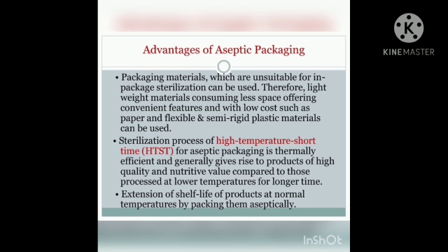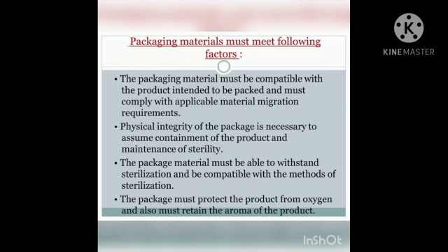Advantages of aseptic packaging. Packaging materials which are unsuitable for in-package sterilization can be used. Therefore, lightweight materials consuming less space, offering convenient features and with low cost, such as paper and flexible or semi-rigid plastic materials, can be used. Sterilization at high temperature for a short time in aseptic packaging is thermally efficient and generally gives rise to products of high quality and nutritive value compared to those processed at low temperatures for a longer time. It also extends the shelf life of products at normal temperature by packing them aseptically.